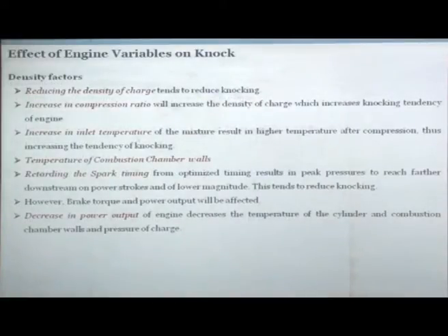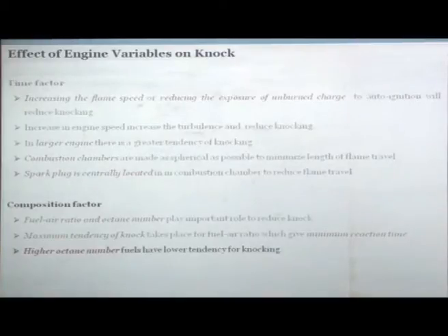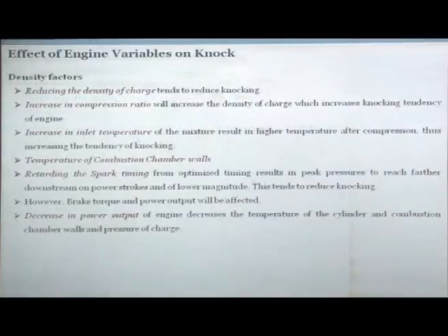Okay. Third is the density factor. So we have discussed already two factors, time factor and composition factor. The third factor is density factor. Reducing the density of the charge reduces the knocking. If you have a very dense charge, the chemical reactions will be faster and faster, and you want to slow down those chemical reactions in the last part of the charge if you want to avoid the knocking.